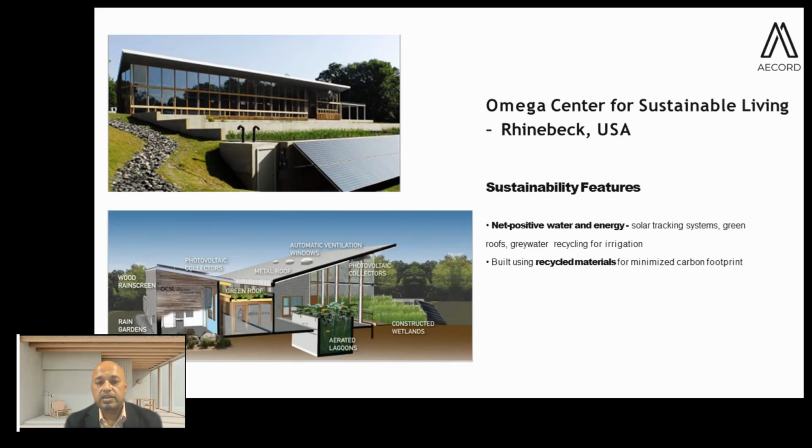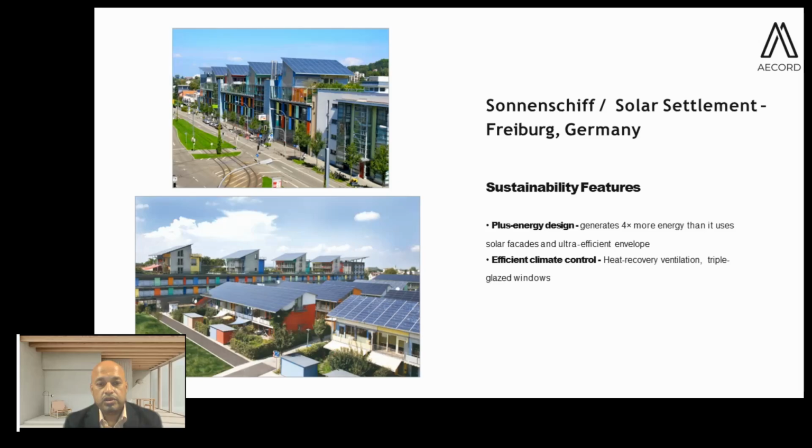Based on that, we decide, as we have three approaches in the market. One is cradle to gate, cradle to grave, and cradle to cradle. So this cradle to cradle is going back completely for recycling. Cradle to gate is okay. It goes to the project, but after the life cycle of the project, you really don't know what happens with the material. So cradle to grave is the second level, which is better than cradle to gate, where you know how the material is reused or disposed. Cradle to cradle is complete or maximum reuse of the material to remanufacture the product or use it in a different way. So this is a project in Germany.